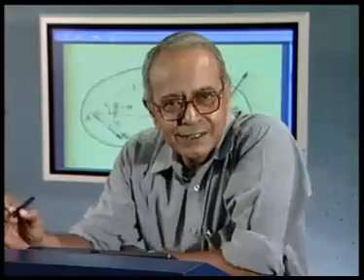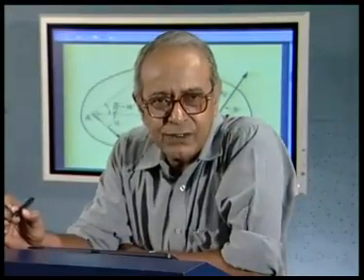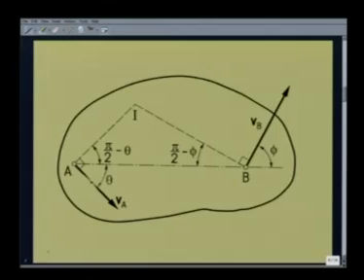To prove the existence of the instantaneous center of velocity for a rigid body under plane motion, let us consider this figure. We consider 2 points, namely A and B, whose velocities are given by Va and Vb. We have already seen that if Va is given and omega is given, then Vb is completely determined. That means both Vb and Va, having 4 components, cannot be independent.